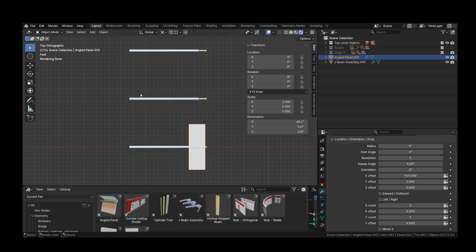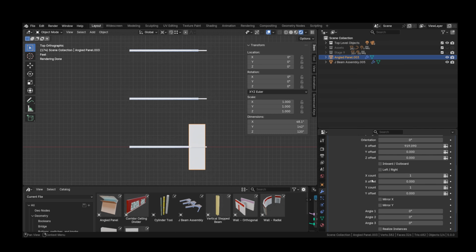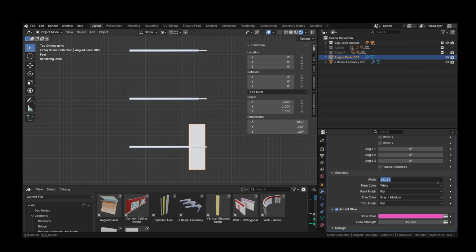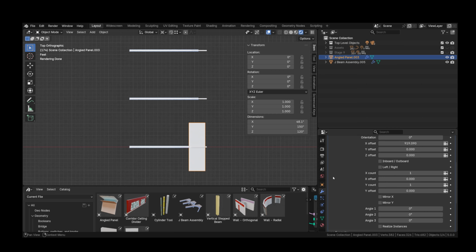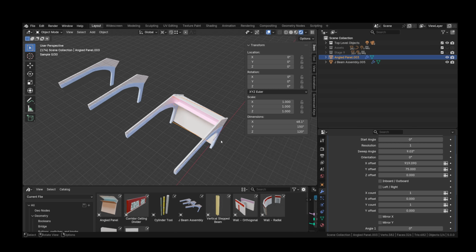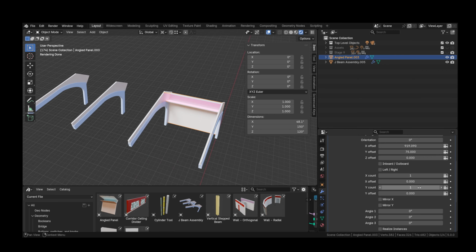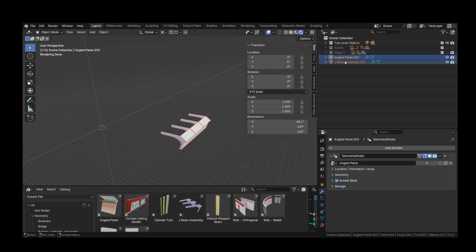These things are spaced at 150 in the Y offset. So my width on this thing in my geometry drop down should be 150, and that should then match exactly. And if I give this piece a Y offset of 75, half of 150, it should put it right in between those first two. Then all I've got left to do is set up the orthogonal pattern, my Y count of 3 and my Y offset of 150, and it finishes that out. All right, delete both of those.